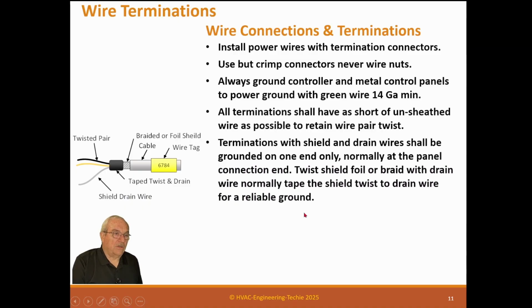And the reason is it's called ground loop interference. What can happen is, because grounds can have different, see how I explain this, they have different ground potential and actually have a possibility of running current from one ground to another ground. Now, this was discovered years and years ago, where we first had telegraph services in the United States, around the world actually. They put batteries in the stations, and what they did is they ran the signal over wire on telephone poles to go somewhere, and then they grounded the other side to just let it go through earth ground.